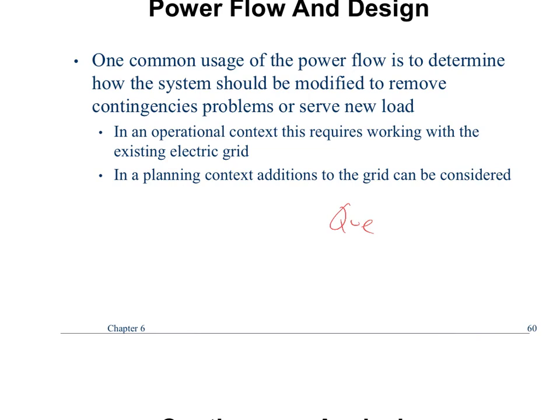So to prevent fires from being started because of PG&E, not because of not prevent fires, but prevent fires being started because of the electrical company, they've just turned off all these lines, and so loads are gone. So what happens is when you lose load, you also have to turn down generation. So you have to tell generators to turn off or turn down.